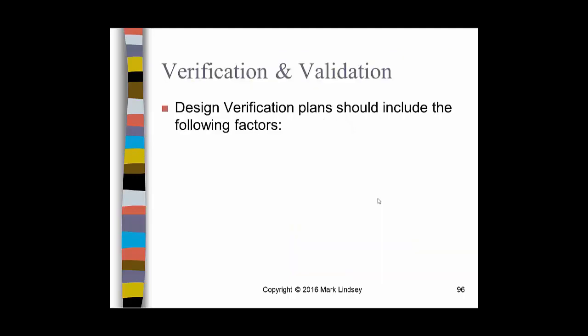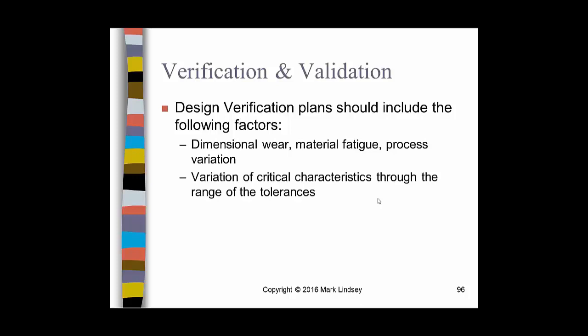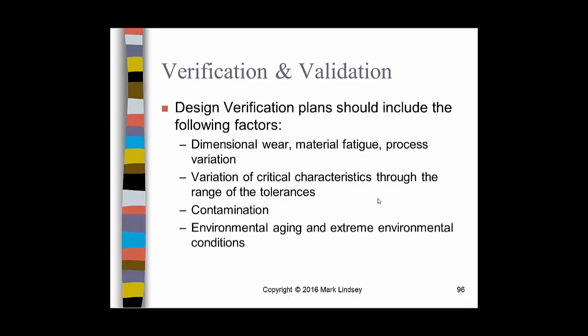So your verification plans should include the following factors: dimensional wear, material fatigue, process variation, variation of critical characteristics through the range of the tolerances, contamination, environmental aging, extreme environmental conditions, and these are all examples, extreme customer usage.